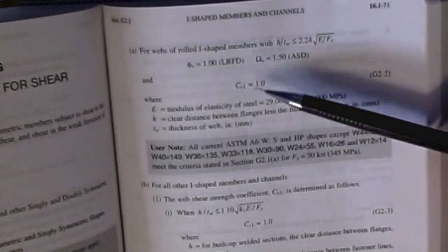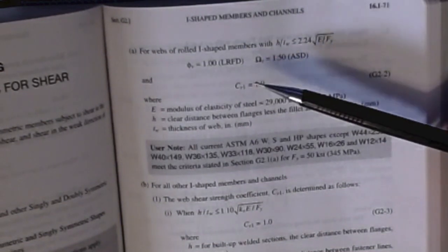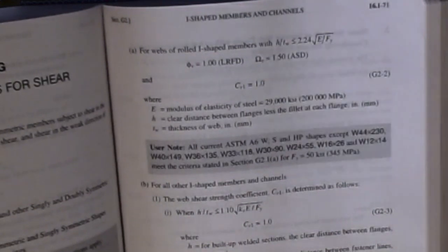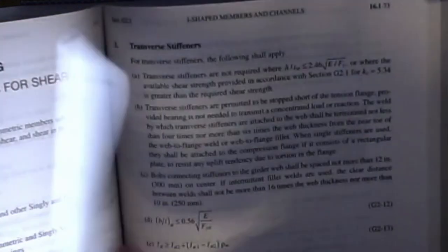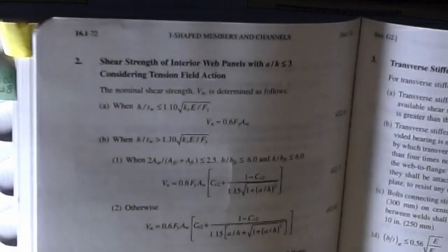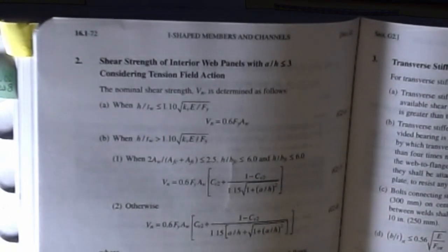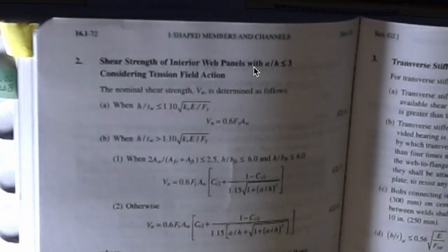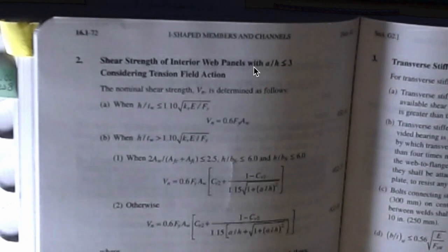But there's also another constant that sneaks in, and that's this Cv, and we'll start to explain this as well as some shortcuts. Then there are some other criteria that we'll get into. It's the rest of the section after this first page where we start to get into trouble. These are the plate girder provisions, and predominantly they have to do with the size dimensions of the panel, which is basically the distance between vertical stiffeners, because one way that you can increase your shear capacity if it becomes a problem is to stabilize the web by welding on vertical plate stiffeners.